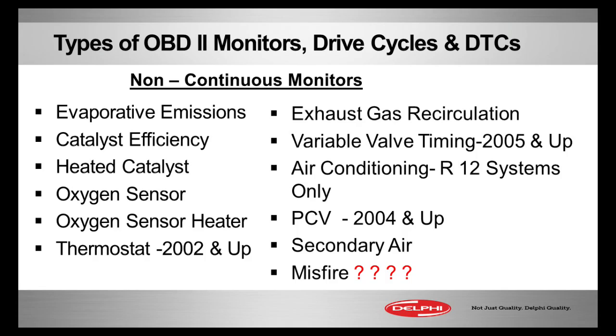And catalytic converters that are heated. Heated catalyst, very, very rare. Some of the high-end Euros, but most of the time you see a cat underneath the car. There's no fuel line going down to it. There's no electrical grid trying to heat it up. So most of the time you will see that say not applicable or unused or something to that effect.